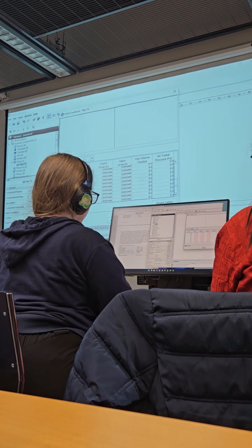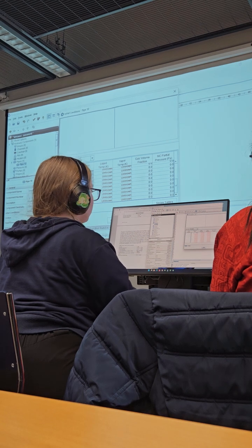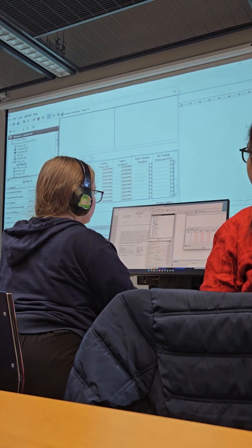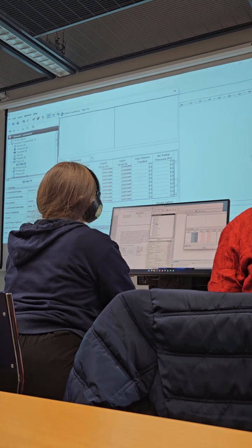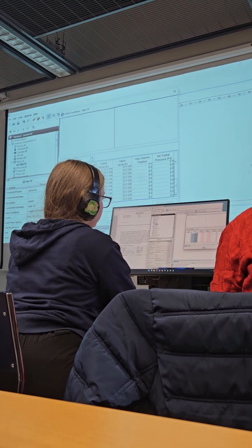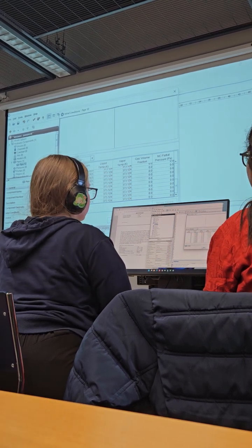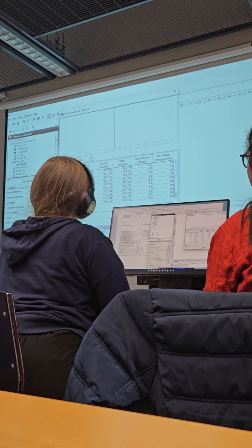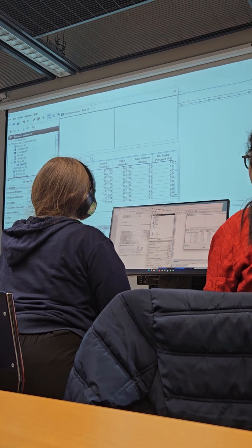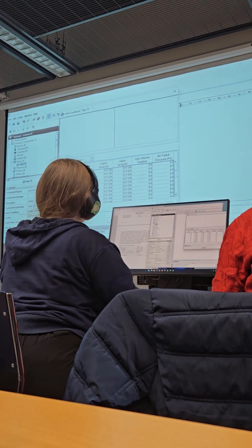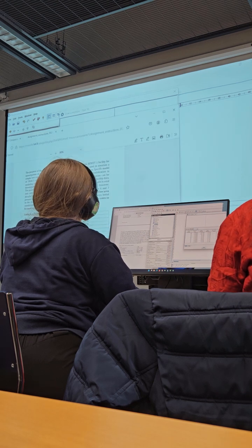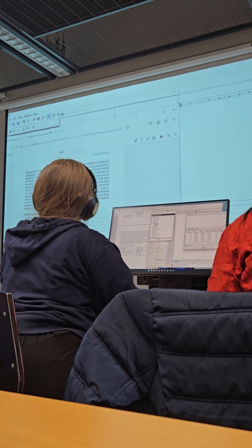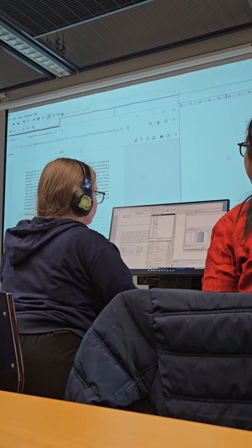So then, since the pressure is 1 bar, it is 101.325. It is atmospheric pressure, or we can just define this as 100,000 Pascal. So then we need to change the liquid temperature and the vapor temperature. Go back. For the liquid, it is 318 kelvins and 400 for the steam.